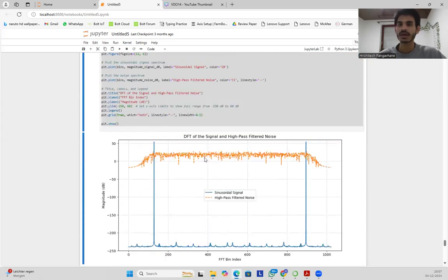Where we are using the windowing technique, while noise shaping or while we are working on delta sigma modulators or analog to digital converters. Basically we have an input signal, and along with that we also have noise. When we plot the FFT of the same input, as we looked at in yesterday's video, we saw that at very low frequencies of the noise, due to the higher attenuation provided by its high pass behavior, even a little change will shift this noise from the bin.